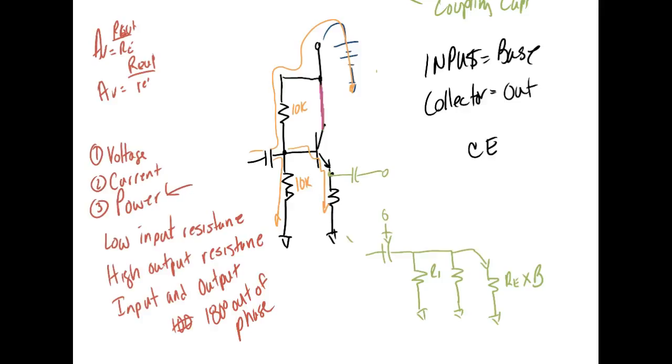Now, how much voltage gain am I going to get out of this guy? Now we can put almost any voltage we want. So let's say I put 10 volts right there. What would the voltage be right there? How much does this junction right here drop? 0.7. So what would the voltage be right there? It'd be 9.3. Right? Don't understand.